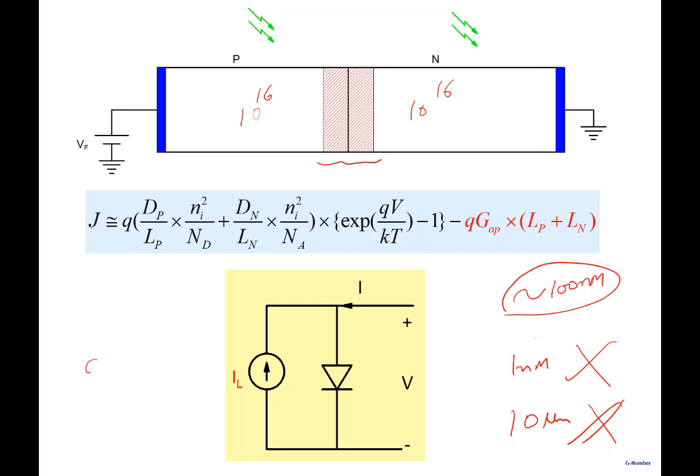What is the thickness that is required to absorb the radiation we just said? 2.3 by lambda. So this was coming out to be hundreds of microns, right? 100, 200 micron. So where is most of the radiation absorbed? This is a big misconception that exists among students, that the photons that are coming in, they get absorbed in the depletion region, and the electric field in the depletion region separates them out. But look, the depletion region thickness is 100 nanometer.